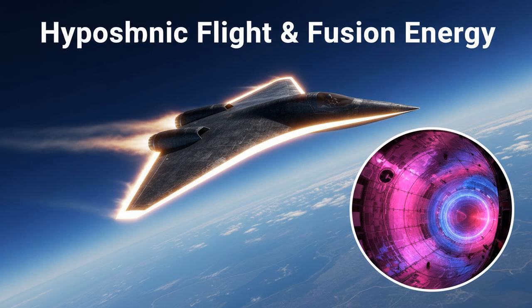Then there is fusion energy, the quest to tame the sun. In the ITER fusion reactor, plasma reaches 150 million degrees Celsius. The walls are bombarded by high-energy neutrons. Metals become radioactive and brittle under this assault. The fix is SiC composites. Silicon carbide has low activation, meaning it does not stay radioactive for thousands of years like steel does. This makes fusion power cleaner and safer.